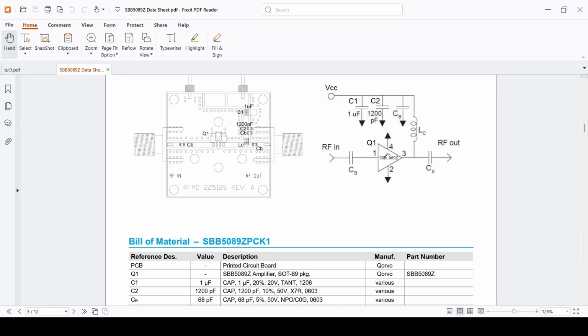We need to know the S parameters of the amplifier, and all these transmission lines, we need their S parameters. But the way to find the S parameter of the transmission line is using a simulator that can extract the information of the transmission line by solving all the Maxwell equations for this transmission line via electromagnetic simulations. We'll try to go over this one by one in the future videos.